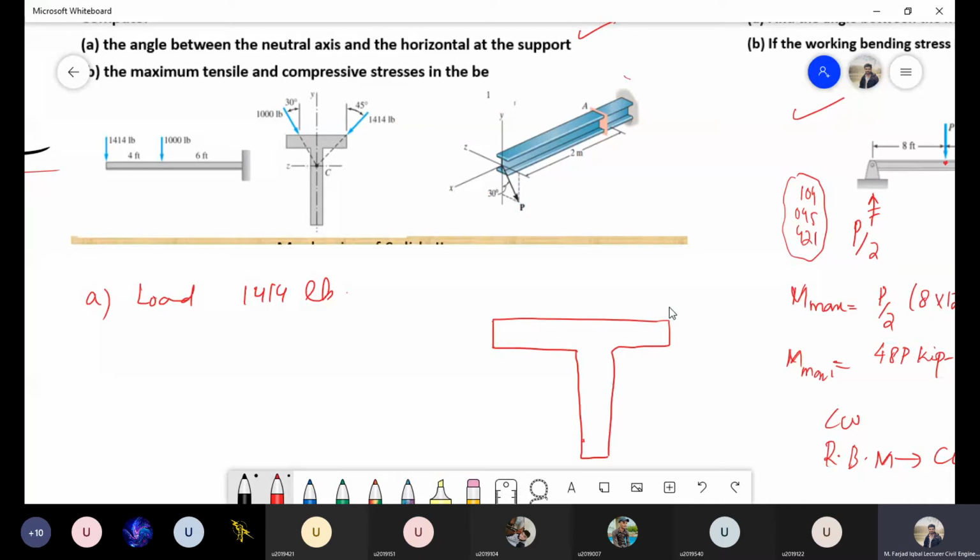And by the way, every time we have to transform them onto the principal axis. You just don't transform these. These are the symmetrical sections, so we know that the principal axes are y and z axis, and they have given us the property. If it is not, if there are some different principal axes, then obviously you will be provided with the inclination of principal axis as well.